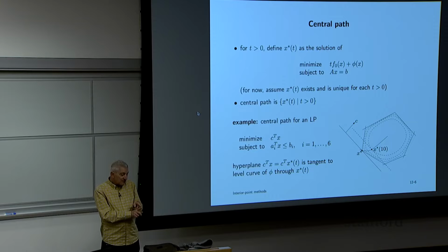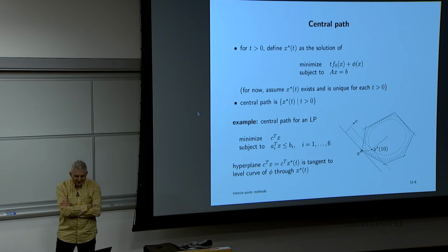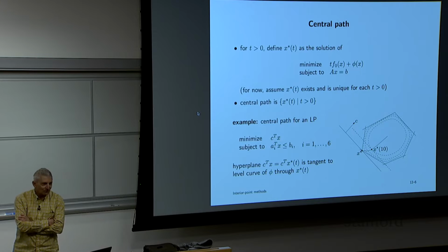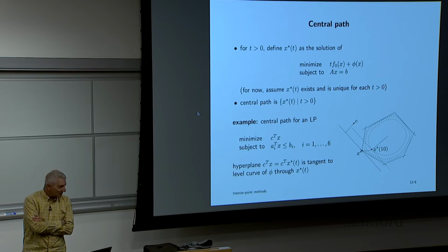Oh, and what you would typically do is, let's say you're using Newton's method each time. Each time you would start Newton's method from where you were before. That's the key. Everybody got this? Right? In fact, this is exactly how SPICE works. How many people know about SPICE or have used it or something? Okay, so some. That's precisely how it computes an equilibrium point.